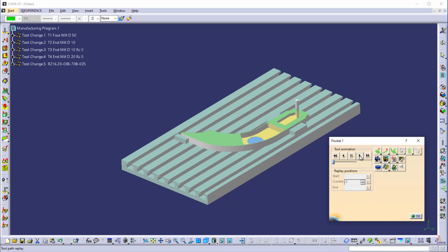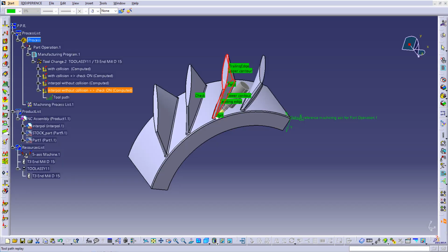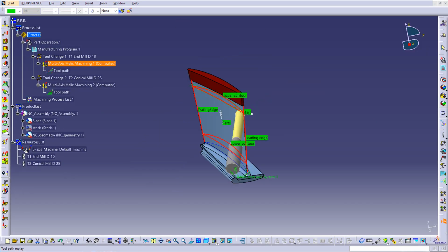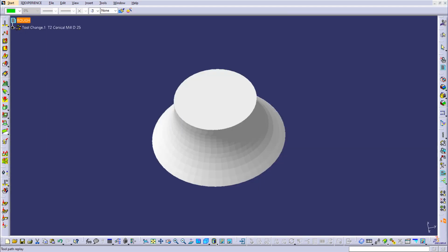Proceeding to cutting operations, the exact cutting processes such as roughing, surfacing, and pocketing are defined to reduce the starting volume into the final part. This step is accelerated with the inclusion of multiple built-in macros to quickly define the tool paths with minimal user input. Catia is then able to simulate the entire process, providing the user with a real-time display of the cutting tool and steadily reducing material, enabling the user to error check the process.